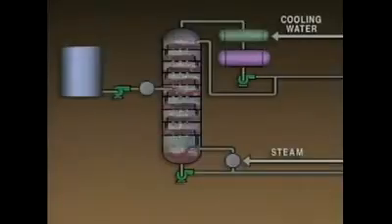In order to maintain the proper temperature gradient, temperatures at critical points in the system must be controlled. Temperatures in a distillation system are typically controlled in three ways. One way is to control the temperature of the feed mixture by using a preheater.